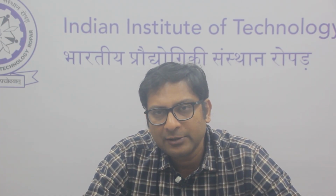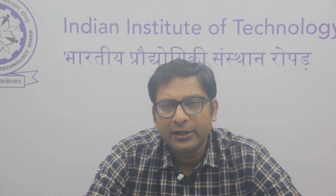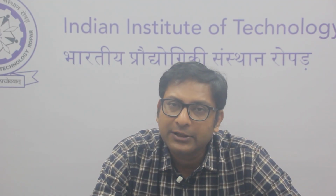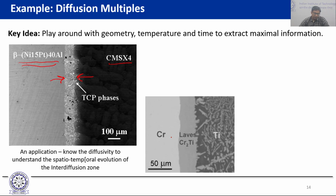The superalloy is an extremely complex chemistry material with lots and lots of different elements, and therefore when you have the bond coat and the superalloy together being exposed to a very high temperature, in between you have the formation of an interdiffusion zone, and in the interdiffusion zone you might be having a bunch of intermetallics forming, which makes it very brittle. So understanding this problem and understanding what is really diffusing fast and what is really promoting the formation of these intermetallic phases is going to be extremely useful for us.